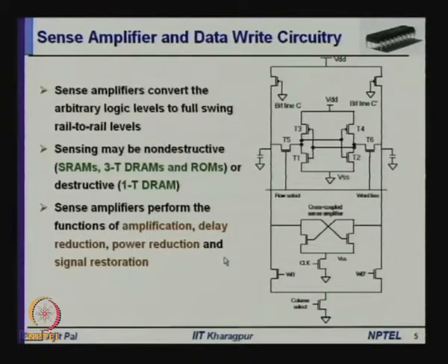Normally, what is happening here is pre-charge followed by charge sharing, and charge sharing is leading to increase of voltage at one bit line, while the complementary bit line is going in the other direction, and that is being sensed by the sense amplifier. It amplifies it, restores the voltage, and does it quickly, and now you get rail to rail voltage, 1 at the bit line and 0 at the bit line bar.